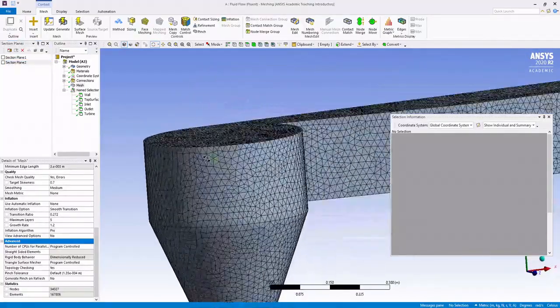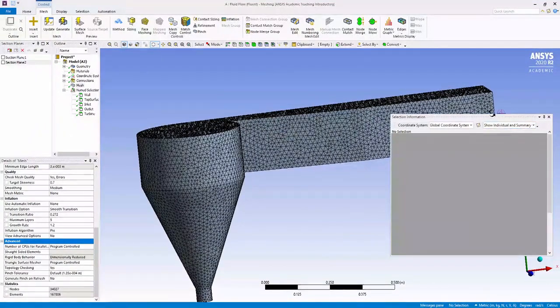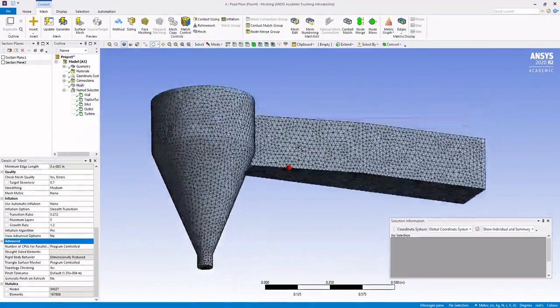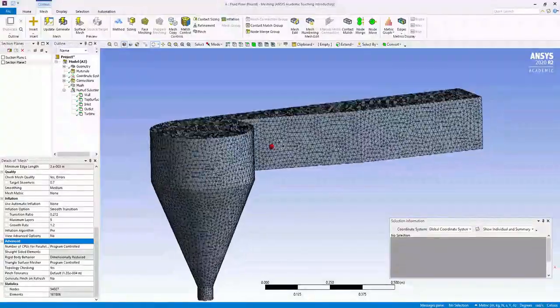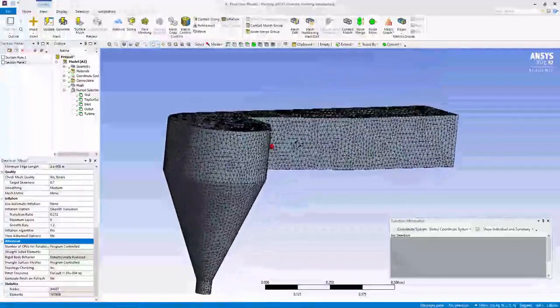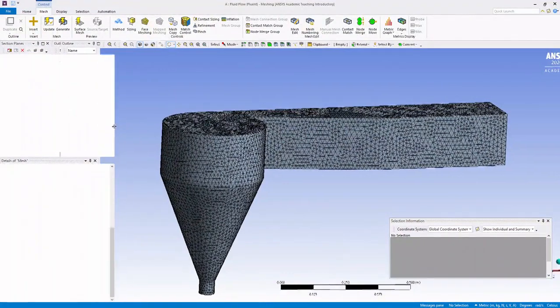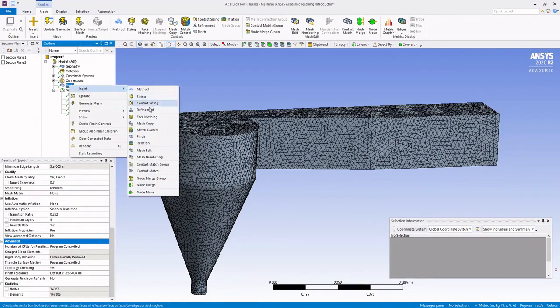now what is important now is the boundary layers. All your walls will include boundary layers. It is essential that you include boundary layers in order to solve the flows close to the wall accurately. You need boundary layers also for your turbine. It will be particularly important for your turbines, your boundary layers. To create boundary layers, you will need inflations.